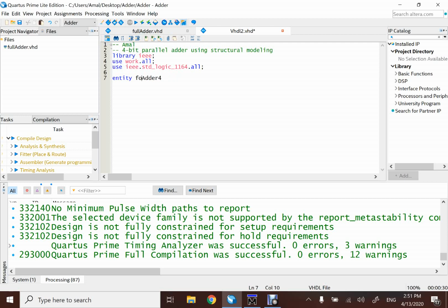So these are descriptive names, yet are allowed by the language. So I'm going to go back to my name from earlier. 4-bit adder. So the entity name I chose is 4-bit adder, and then I'll say is, and then end the entity name. You can always copy it to avoid any typos, and then semicolon.